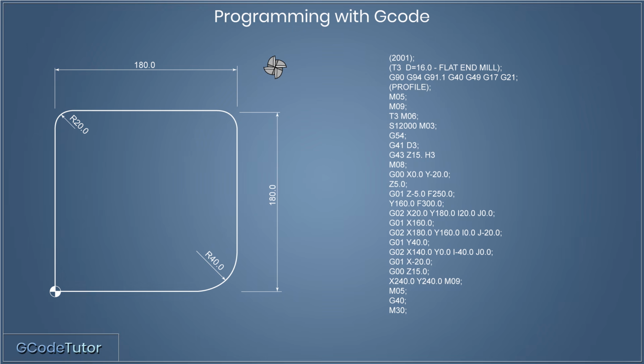So that was a rundown of a very basic program cutting a simple shape on a CNC router. Now for more complex shapes, everything would be the same. The layout would be the same, the M codes, the G codes, and the safety line at the beginning, and the way we end it using G40, M30, etc. The only thing that would make it more complex is there'd be more lines of positional code, the G01s, the G02s, and the G00s. So that is how we write a program using G code for our CNC routers.